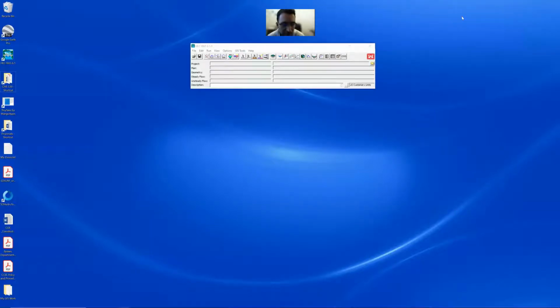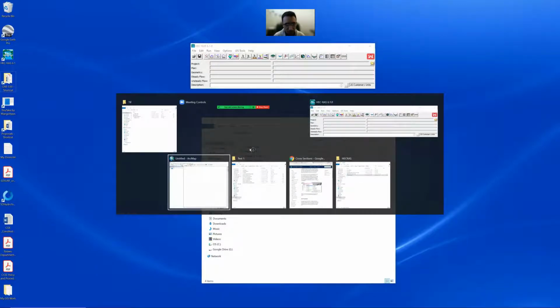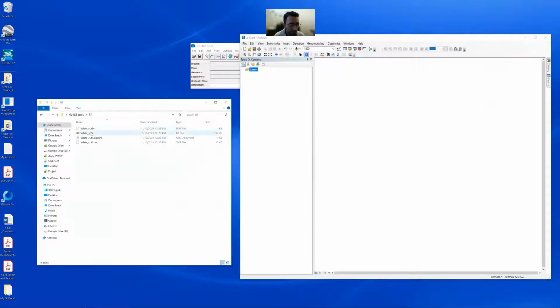Today, we're going to learn a little bit about how to process the TIFF file that we created so we can make a HEC-RAS model out of it. So right here, I've saved the work that I did. I showed you in the previous video. I first defined a shapefile for the boundary of the area, and then I created a TIFF file from the SANDAG layer. Of course, first step is to make sure what you have for the TIFF makes sense,